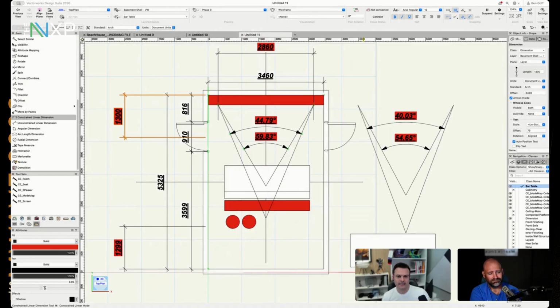going to be like Dumbo's ears. All I can say to that is you need better doors. My door does not move. No. So even if your door's not that solid, we build really heavy steel-lined doors, right? Really, really high mass. Even if they're not, there should be a rubber seal going around the door jamb that means that once that door has closed against its latch, it should effectively be under pressure.